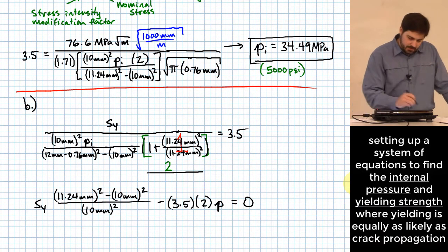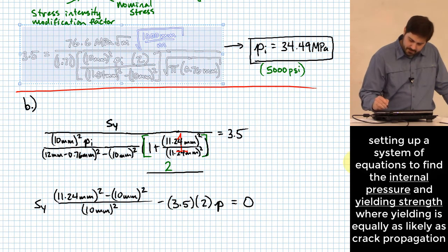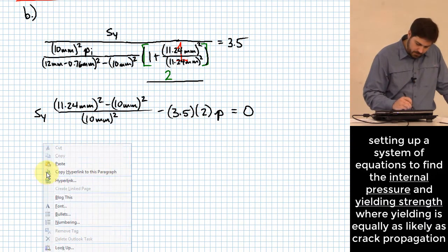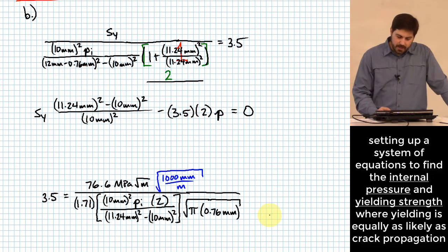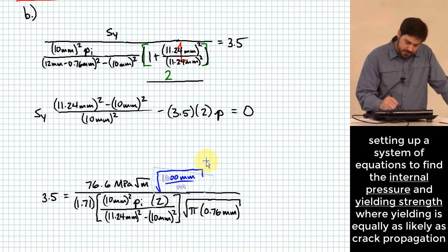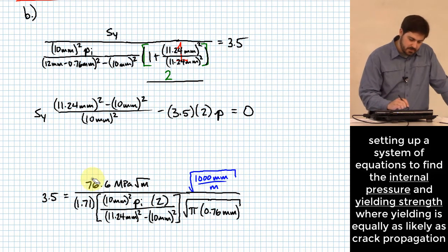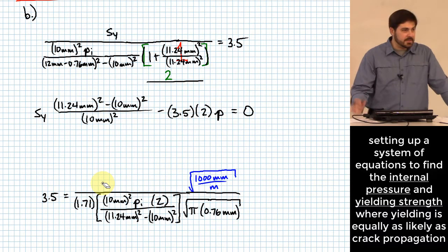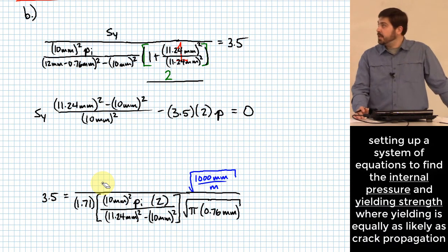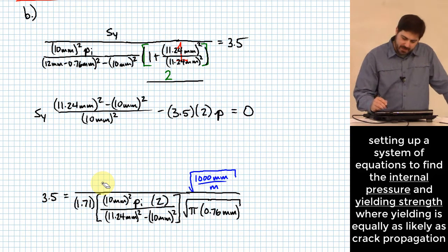Okay. Well, let me actually take this one. Once I take this one, something will change for this equation, and that is the fracture toughness. Keep in mind, the fracture toughness changes when we change the material strength. So I now won't have just a plain value of fracture toughness. I need to express that fracture toughness in terms of my yielding strength. Where do I get that?